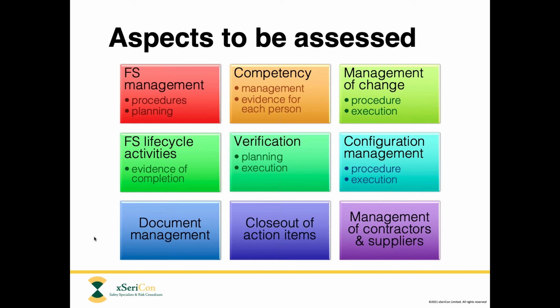The fourth area is the individual life cycle activities. So this means, for example, the HAZOP study, the SIL determination study, the preliminary design of the safety instrumented system, the SIL verification, and all of these steps one after the other. We would like to see evidence that each of these steps has actually been executed and completed. And a very good way to provide that evidence is by showing us number 5, which is verification.